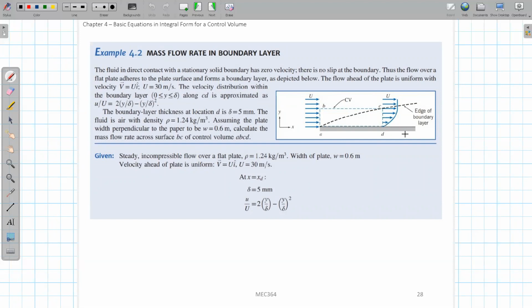So when you have flow over this flat plate, because the flow has viscosity, there will be friction between the flow and this solid surface. At the location of the wall here, because we assume the no-slip boundary condition, the velocity of the flow will become 0. Then in the region very far away from the wall, the flow velocity will just be equal to the free stream velocity. That means there will form a very small region. The thickness of this region will be very small, and this region is very close to the wall, so inside this region you will have a velocity gradient. This is the u direction velocity gradient, and inside this region the velocity will quickly change from 0 to the free stream velocity.